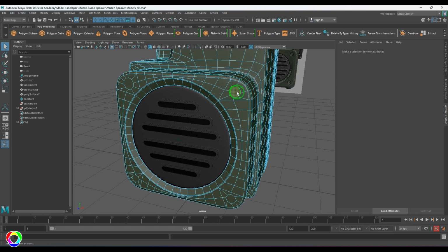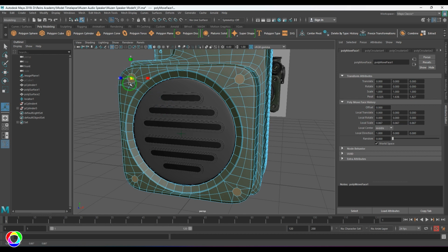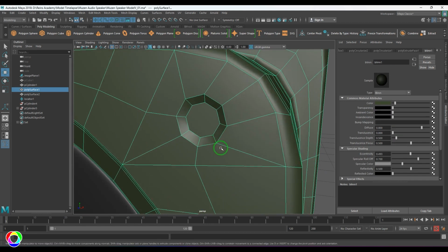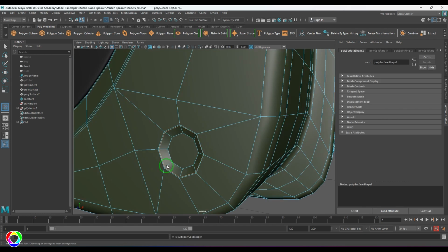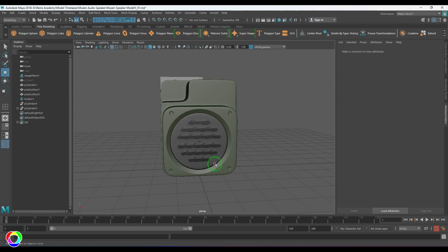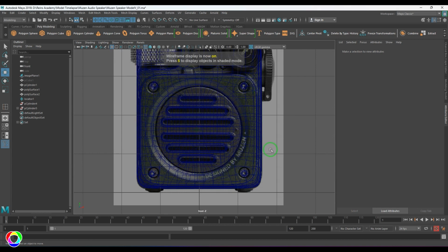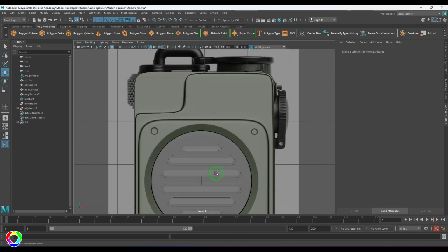So once I've got that, I'm going to select all the faces, use this tool called transform component tool, and then scale it to the same size and then extrude them like that. I'm going to add lines around it. So I've got those 4 holes on the 4 corners. I can add the screws and all that once I have completed it. There's no hurry about it.